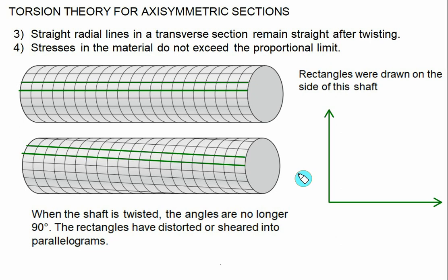Now since we are familiar with the proportional limit and the material property, this time the graph is drawn as shear stress versus shear strain. Initially we have a straight line distribution, then non-linear, then strain hardening, and then we get the ultimate value, up to where we have the linear distribution. That will be called the proportional limit, and this proportional limit is simply taken as SYS, the yield stress in shear. Basically there is no difference between the upper yield point and the lower yield point, so SYS will be the limit we take here, and we have linear distribution here.